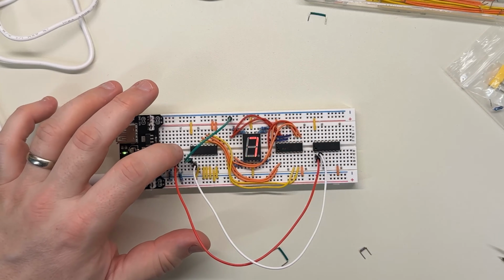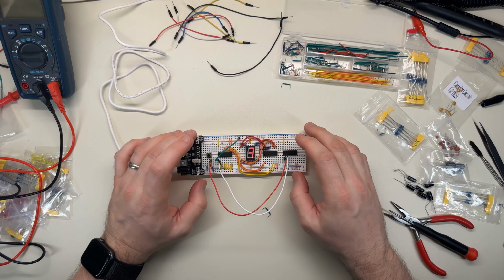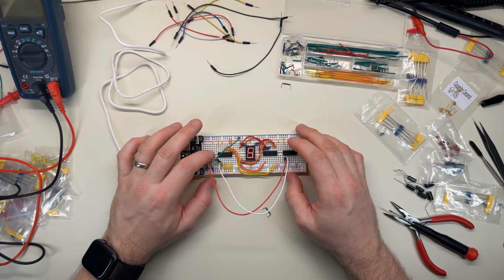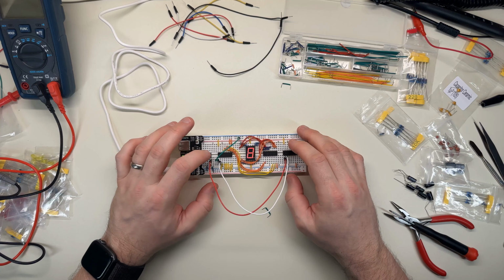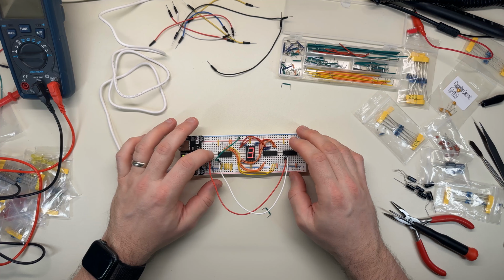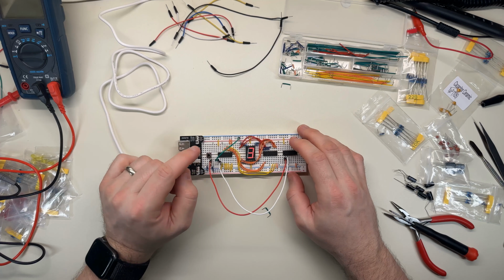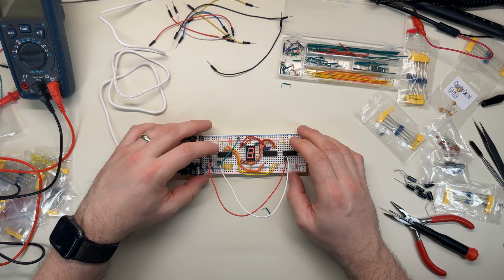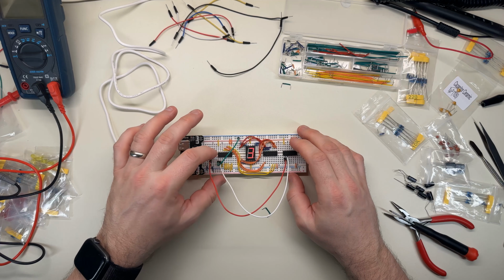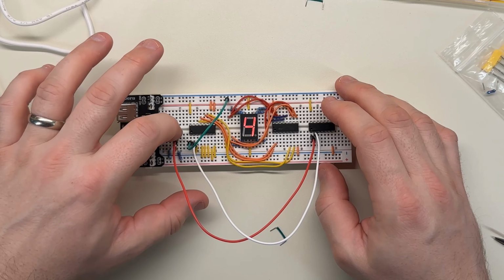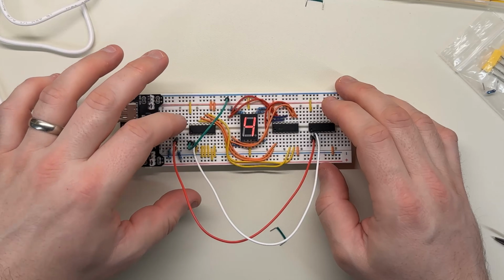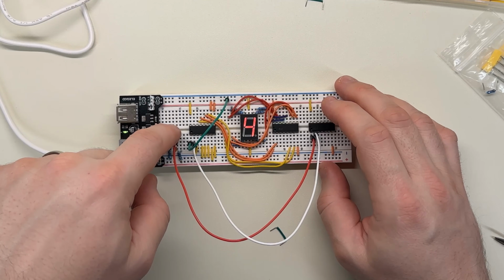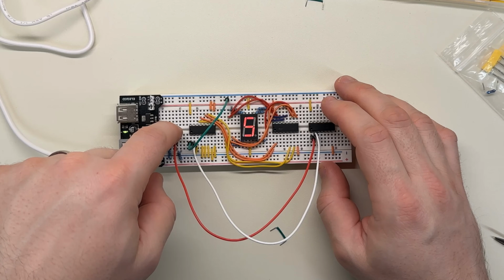Now, it still bounces a little bit. Since I don't have an oscilloscope, I can't check and see how long this is bouncing for, but I'm starting to suspect that this switch is maybe bouncier than I first anticipated, and the only reason it worked well before I put the debounce in there was because of the way it was hooked up. It only incremented when I lifted my finger, and you'll notice now, because it's an inverted signal, it now triggers on press, right?